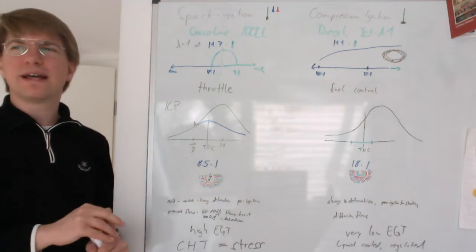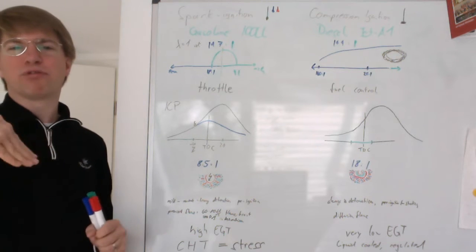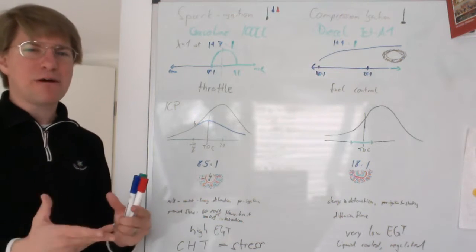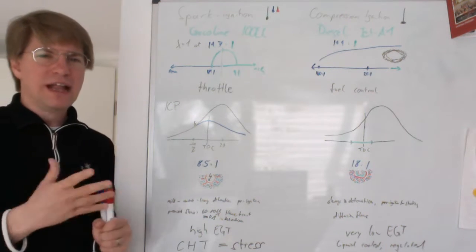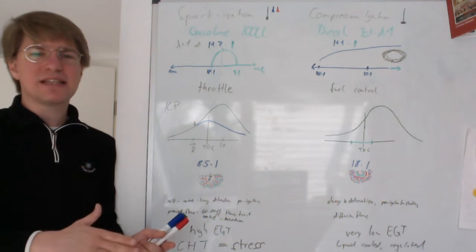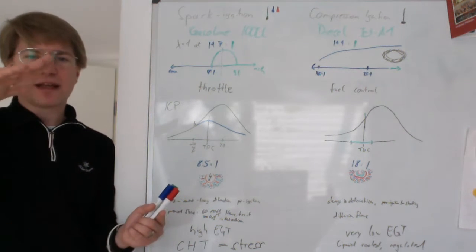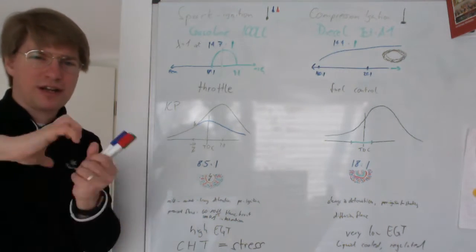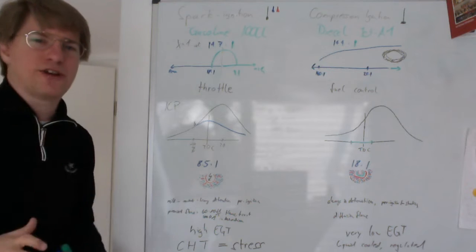I say more or less because while we can keep the pressure up with the turbocharger, we are also heating up the air while we compress it in the turbocharger, and that heated air is still less dense than the air at sea level that we're taking in at ambient pressure and not running through the turbocharger and compressing it.